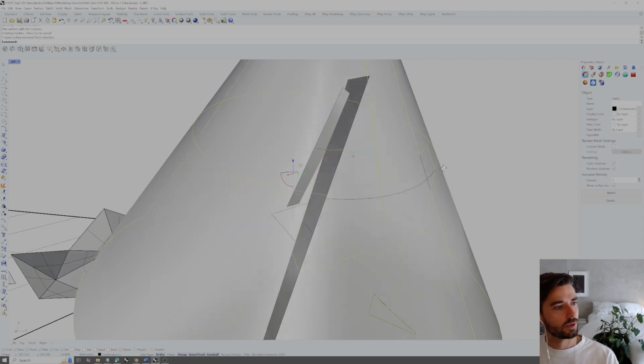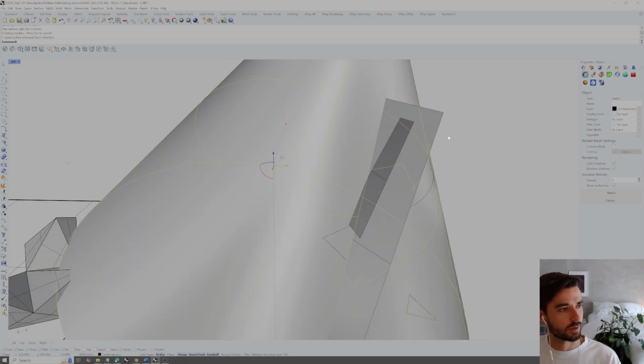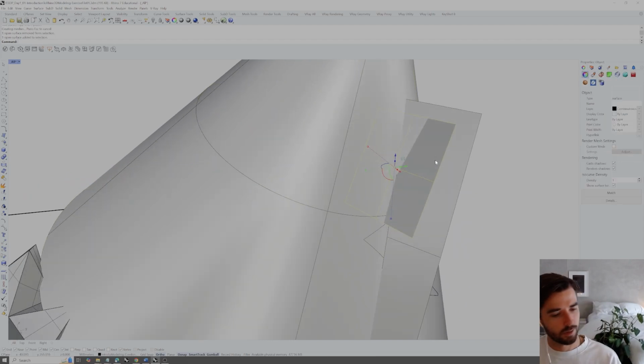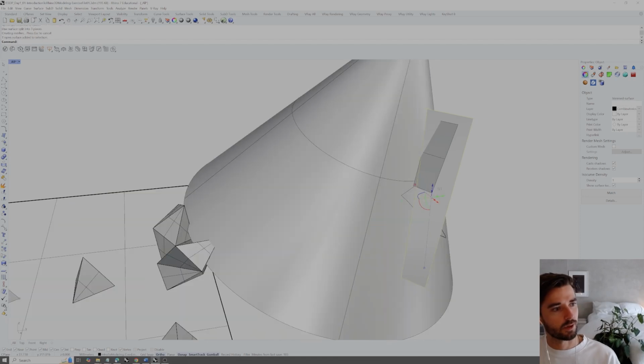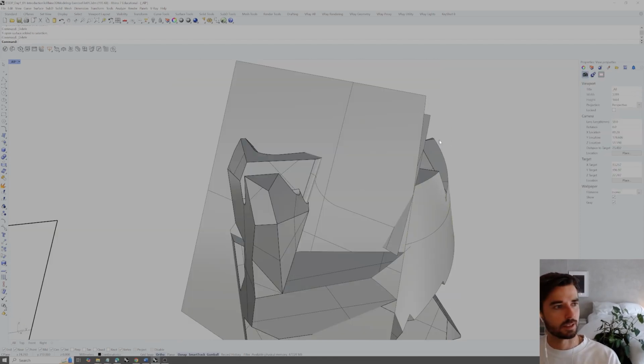And then we'll still use the rest as a splitting or cutting geometry for the other two planes. So what I'm going to do here is now I'll split this. I think we'll have to do the cone. I'll split this one with the cone as well. And we'll just delete these extra bits and then delete the cone as well.